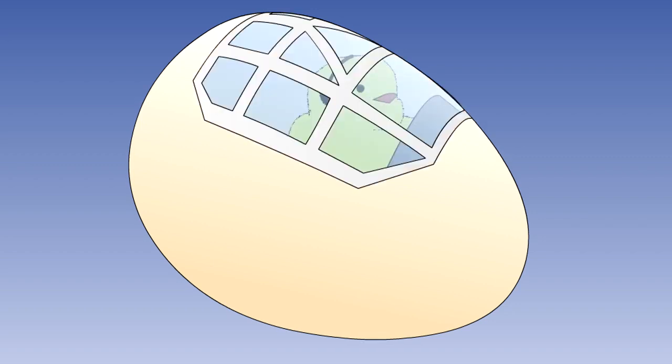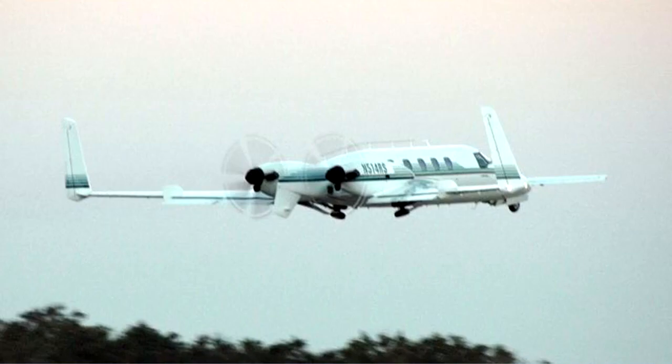To be a true monocoque, the structure would have no apertures in it at all. But for practical purposes, they have to be provided for access and maintenance. The apertures need to be reinforced so that the integrity of the structure is maintained. Once the aircraft doors are closed and all the hatches and access panels are fitted, the fuselage is, to all intents and purposes, a monocoque structure. One of the few examples of monocoque fuselage constructions is the Beech Starship.